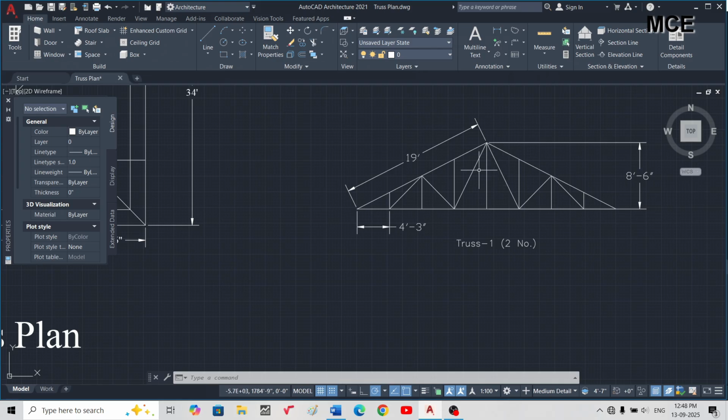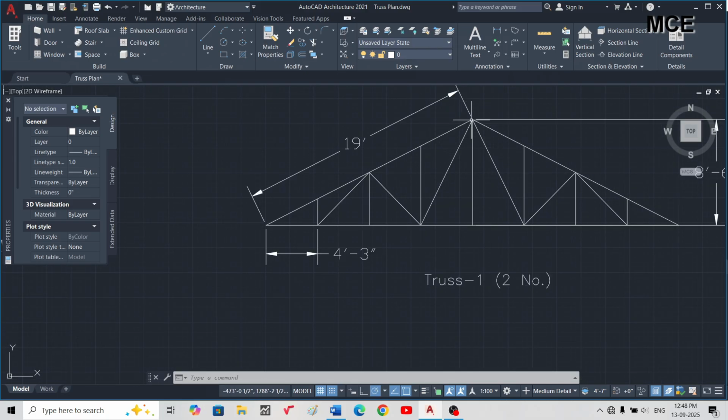Or if you already have good experience with steel structures, you can decide from the structures in your local area what type of sections they have used, and then appropriately take the sections. If the loading is heavy, then you have to go for the channel sections, and if the loading is less, you can take less weight sections like the angle section or the hollow sections.